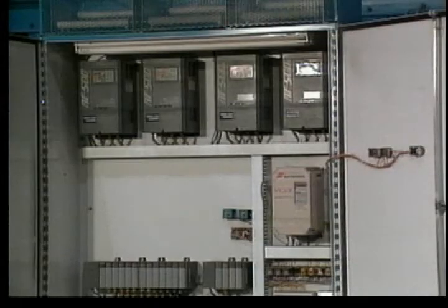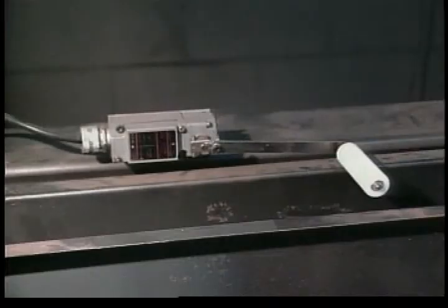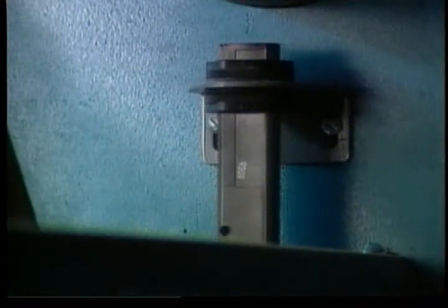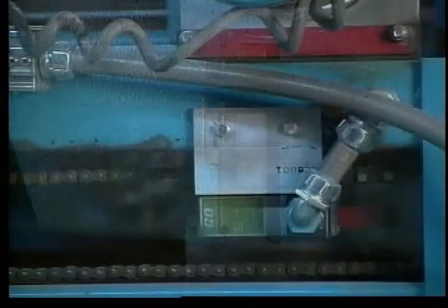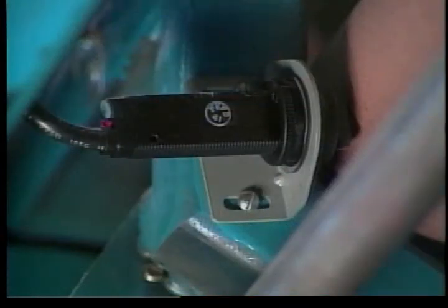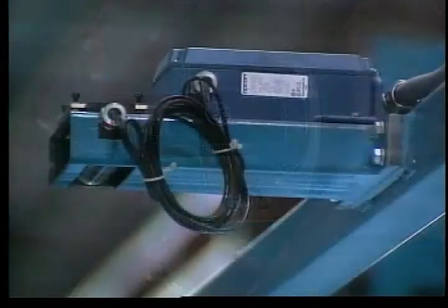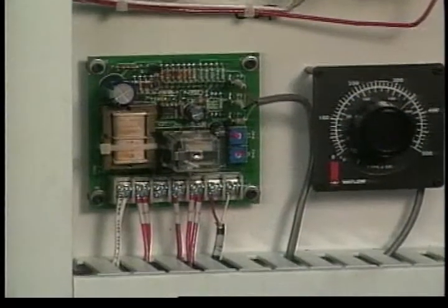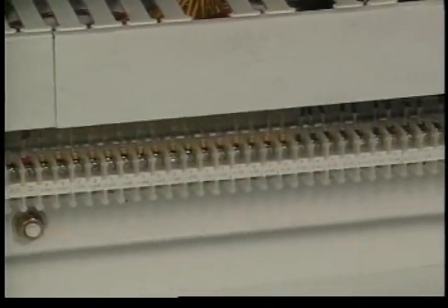In order to perform its job correctly, an inverter-based system must have reliable feedback from field devices. This means that every limit switch, sensor, encoder, or other device in the system must be working correctly and transmitting accurate signals. Each device must be correctly mounted, clean, and undamaged. Every connection must be tight, and every wire must be properly grounded and shielded. The system should include surge suppressors, and power and control wiring should be run in separate conduits.